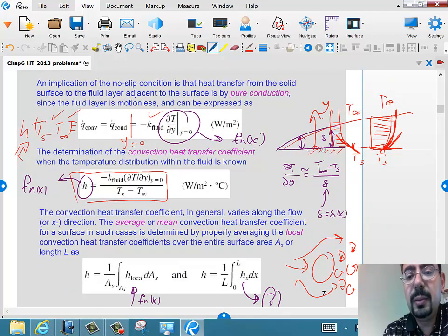This is the plate, all right? I'm not saying it's insulated, I'm just plotting the wall. So as the air comes in fresh, with U infinity and T infinity, it starts growing this boundary layer. Meaning that the velocity here is probably uniform like this, not knowing that there is a wall. And then when it starts seeing the wall, a boundary layer will grow.